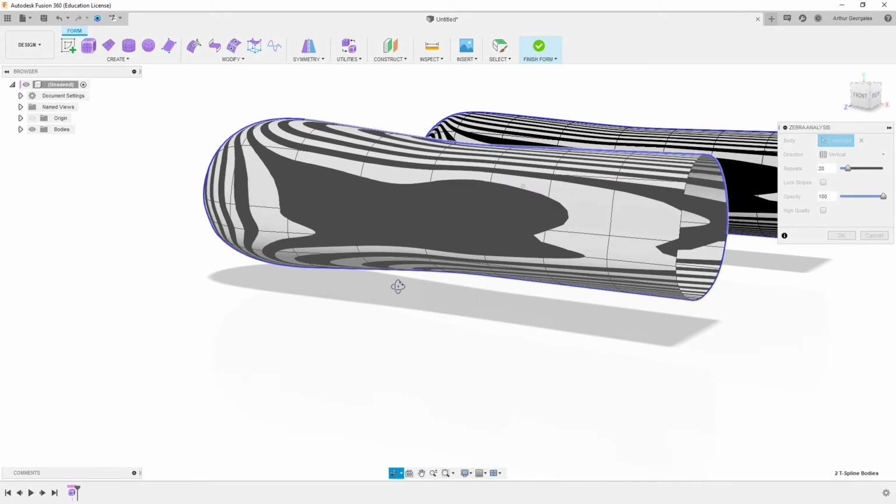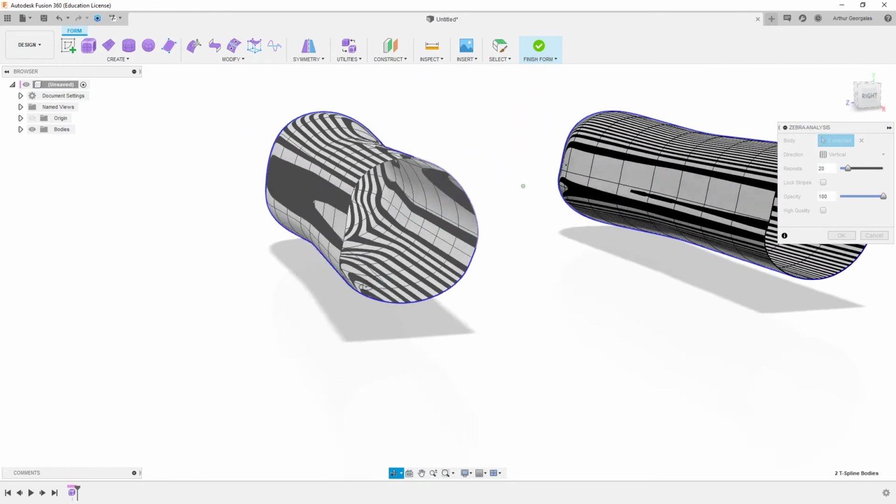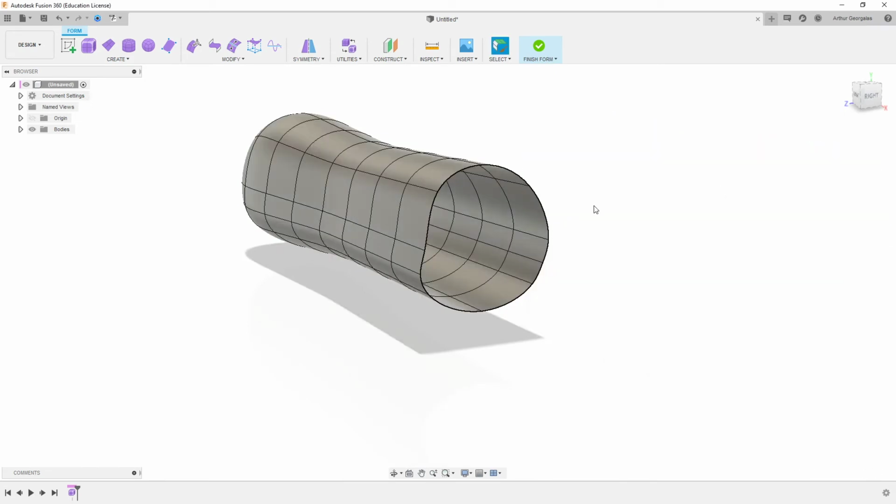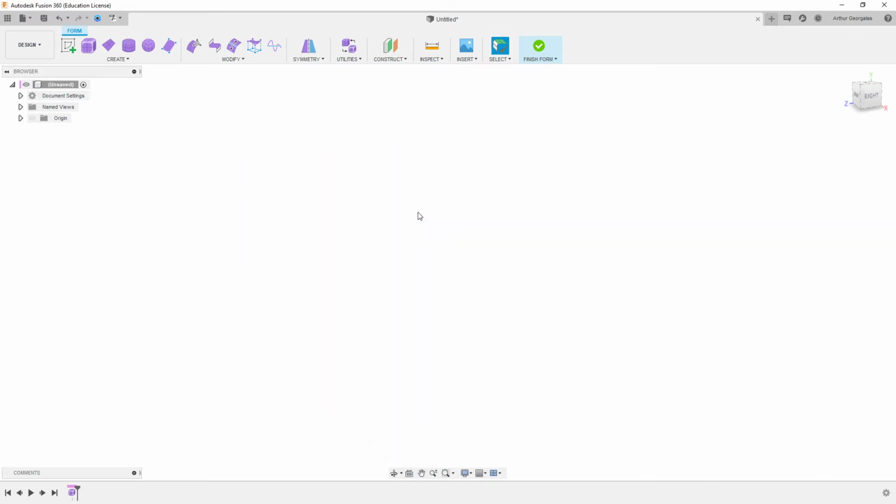So trying to understand the whole quad ball thing can be a bit complex. Just use the quad balls. I wouldn't use a sphere in any case. The quad ball's a lot easier to manipulate and a bit smarter when using T-splines.